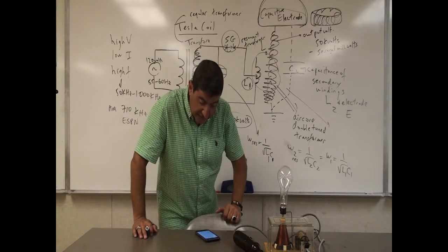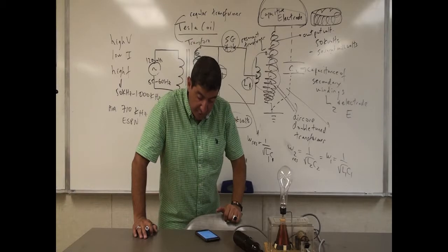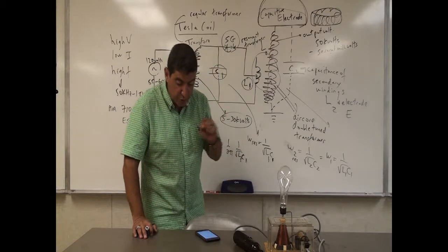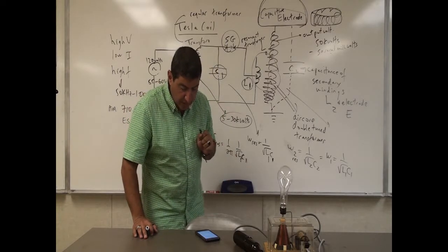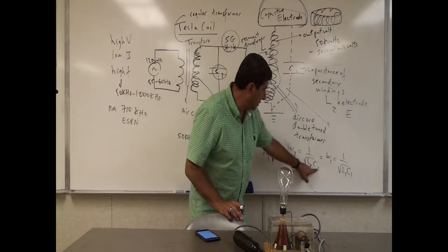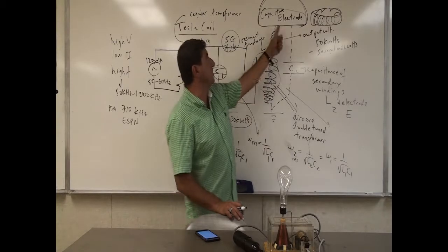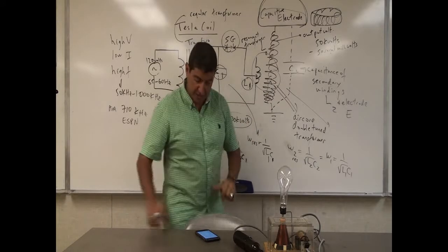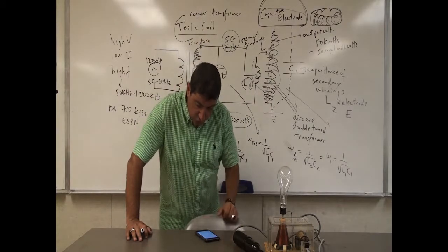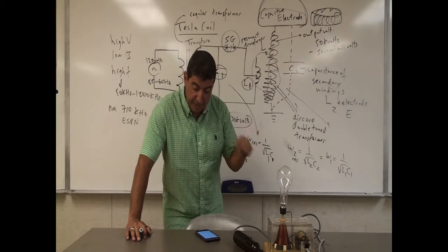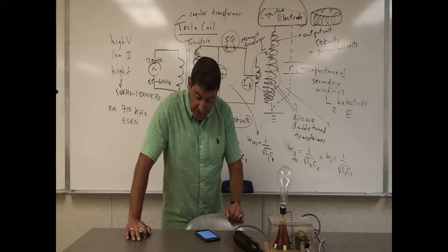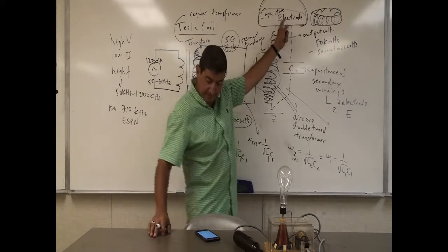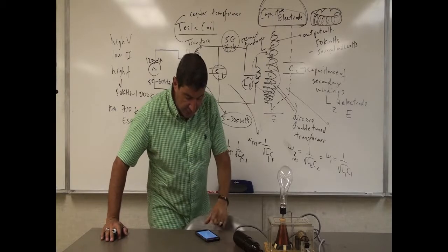The secondary is not connected to an actual capacitor, but it also functions as an LC circuit. The inductance of L2 resonates with the stray capacitance C2. So L2 and C2 resonate together. So what is C2? It's a measure of the capacitance of the electrode and its own windings. C2 is the sum of the stray parasitic capacitance between the windings of the coil and the capacitance of the toroidal metal electrode, which is up here, attached to the high voltage terminal.